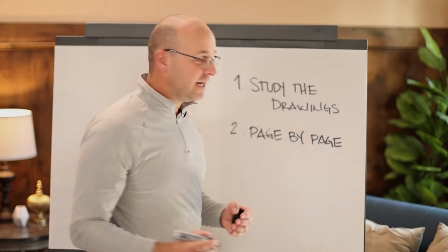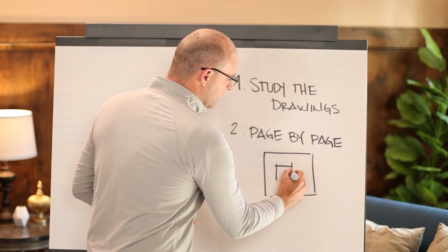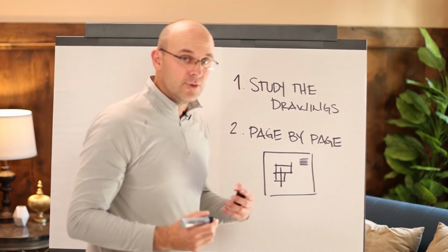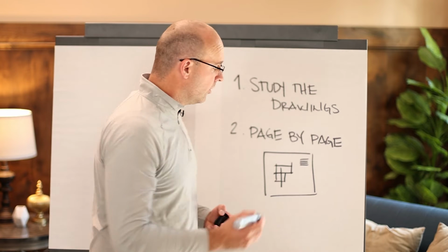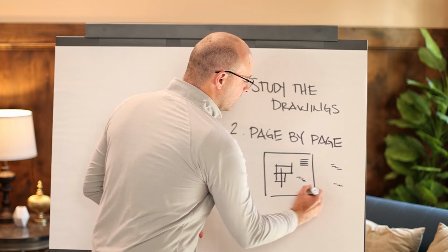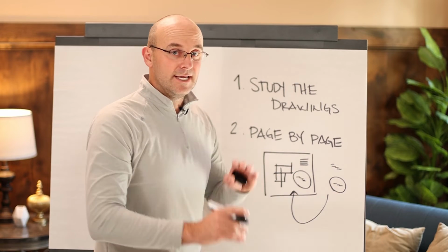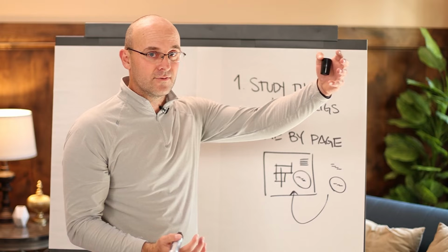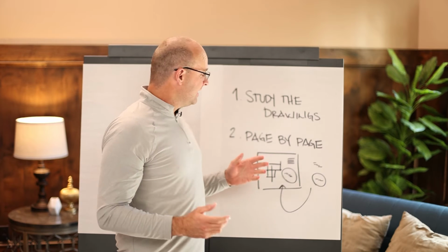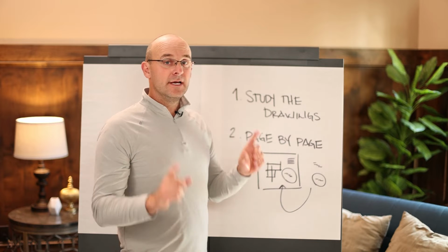And on each one of these pages, as you study the drawings and you look at the building components in the actual drawing set, and as you read the notes and really get an understanding of what's on that page, right there on that page or out to the side or in your scheduling software, you go ahead and create the sequence for the work that's on that page. Yes, it's disconnected. Yes, it's not tied into the overall schedule, but you can just schedule that single page. You can easily go through that whole set of documents and not get overwhelmed and literally schedule a sequence page by page.